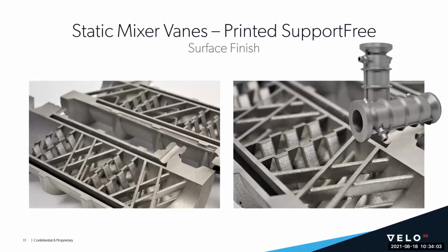Looking at those, you can expect a surface finish on an underside like that at 20 degrees to be in the ballpark of about 12 microns SA. You can also see the quality of the inlet passage over here at the circular passage.